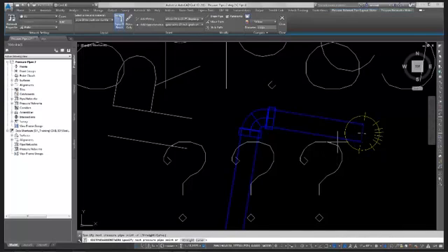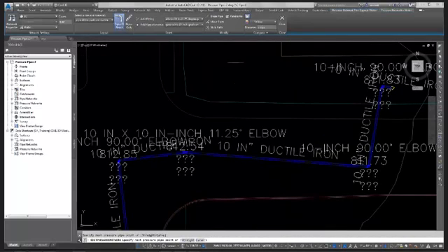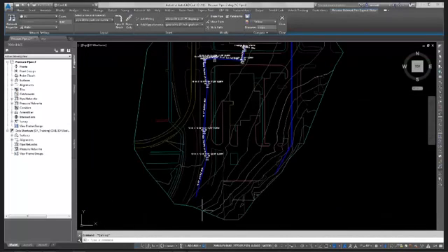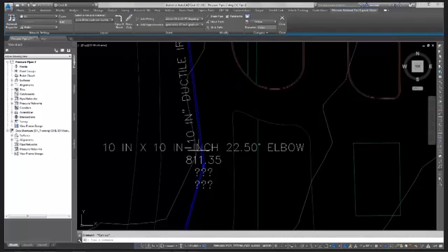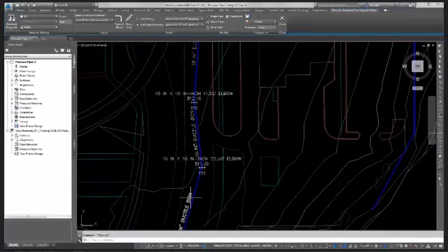The downfall to pressure pipe networks is that 8-foot hold down that I put in right up in here. It held the 8-foot here and the 8-foot at every time I clicked. It did not hold that 8-foot in the middle of the pipe. So you may have a lot of relief on your site, or you might have a swale, you might have a hill. If you go through that hill or that swale and you don't click at the peak or in the swale, it's not going to know to hold that 8-foot. It's going to go straight across.